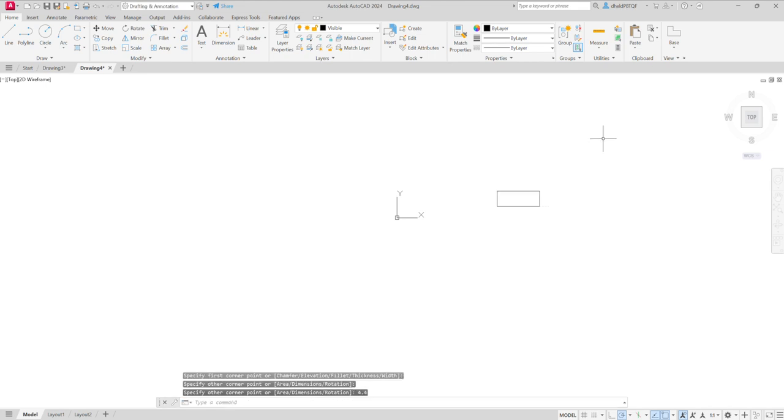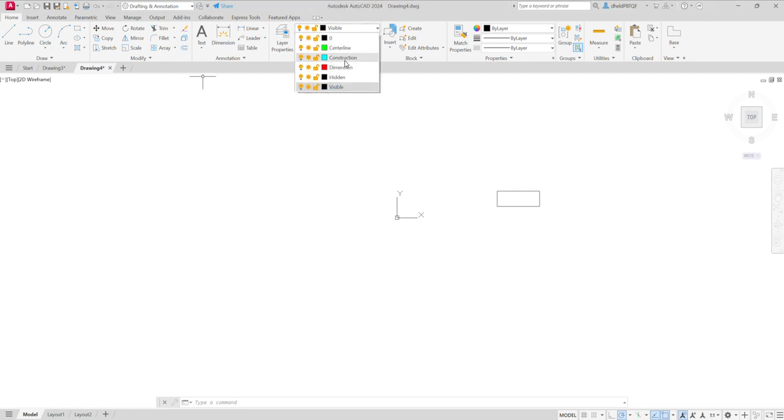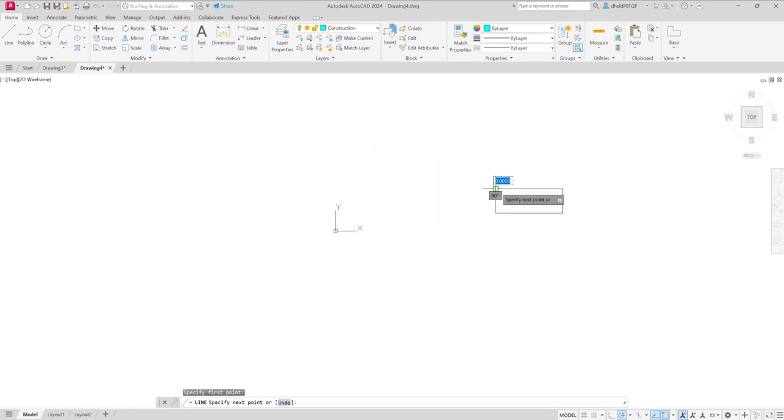Like that. Okay? And then I'm going to switch to a construction line, and I'm going to create a line, and I'm going to go right on this corner and make sure I'm at 90 degrees, and I'm going to type in 3.2, and then I'm going to turn it this way and make sure at 0 degrees, and I'm going to type 3.2, and then I'm going to hit escape.